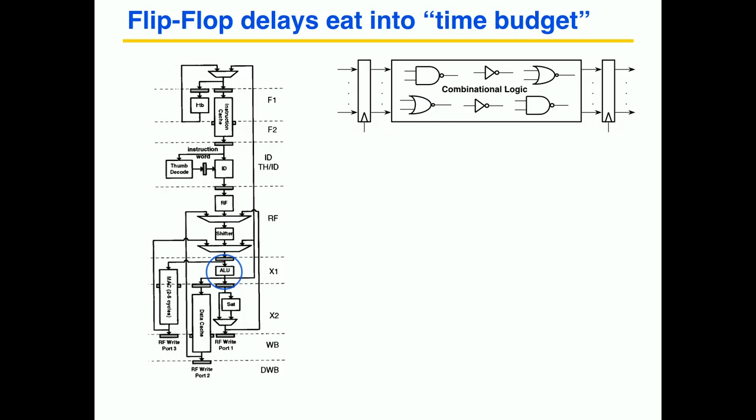Because here's some processor design, and there's an ALU here in the processor. And this is similar to what your RISC-V processor will look like if you take it in the lab. And somewhere in here you'll have a pipeline stage. There's a register, it goes through the ALU, and the result goes into another register. Right? This would be a typical stage of logic, or pipeline stage, you'd see inside a processor. In fact, I picked this one with the ALU because often the ALU is one of the longest paths anywhere in the design. Because if it's a 64-bit processor, it takes a lot of logic gates to add 64-bit numbers together. So there's a chance that could be one of the critical paths, or the critical path, for your design.